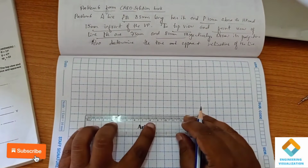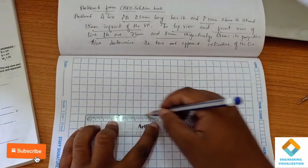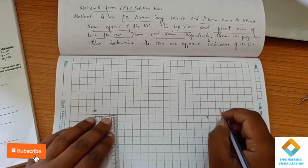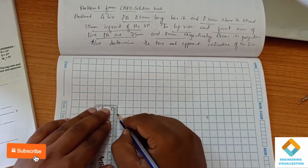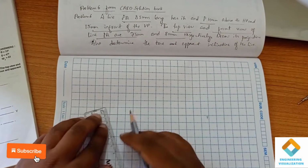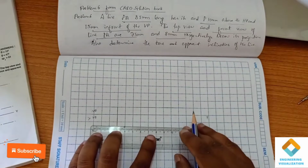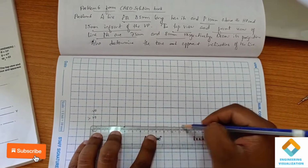First I am going to draw an XY line here, with VP and HP. The end point P is 10 mm above HP and 15 mm in front of VP. Here I am going to draw locus lines, wherever the end points are.